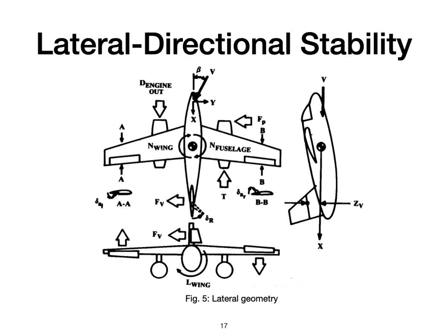The yaw deals with directional and the roll deals with lateral. It is important to realize that both are driven by the yaw angle beta and that the roll angle actually has no direct effect upon any of the moments. Furthermore, the deflections of either rudder or aileron will produce moments in both yaw and roll.